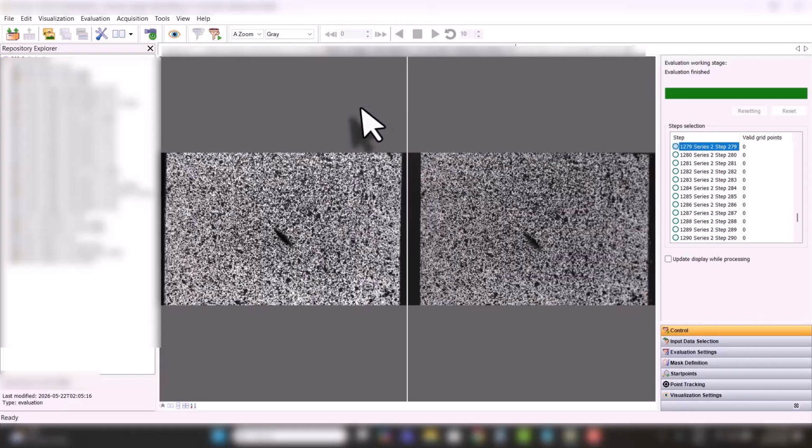Okay, so what's different if you're trying to refine a DIC correlation? This is really near an edge of interest. We don't care about the correlation near these edges, but these are edges that we care about. And with a crack tip, it's a similar idea, but the crack tip is a little bit different in that the speckle pattern is degrading at the crack tip. So it's a combination of speckle pattern degradation and trying to correlate near an edge. Here, the speckle pattern is remaining intact for the most part.